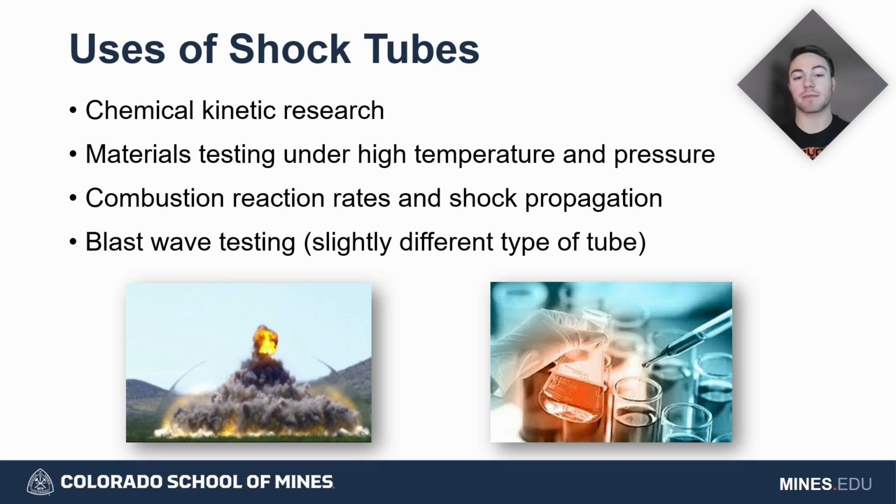And then blast wave testing kind of goes with materials testing. If you have a large enough shock tube or an environment that needs to be tested that you could fit in one, you can then use the shock tube to test the shock wave that is created against whatever system you have in there. Now mine is definitely more of a standard shock tube where you can put a diaphragm material at the end than a blast wave, but the same principles apply. And again, CFD is probably your better move for modeling this kind of device.